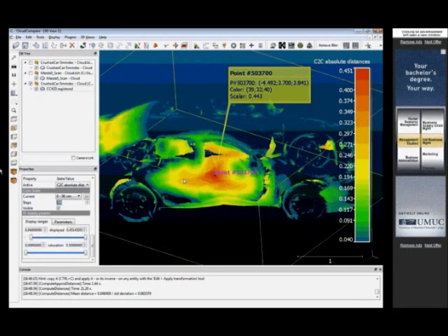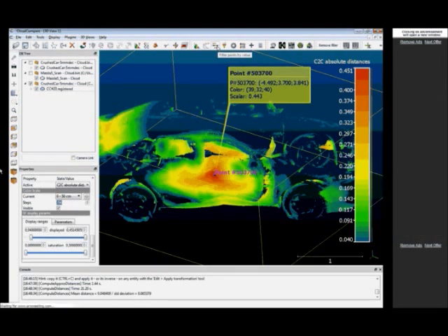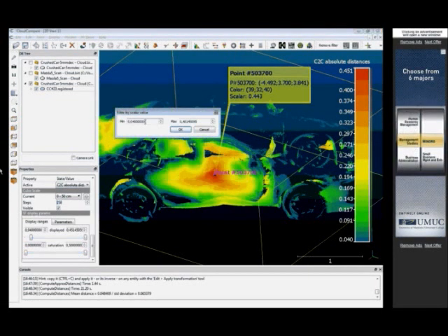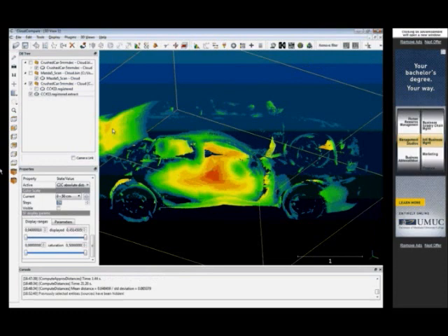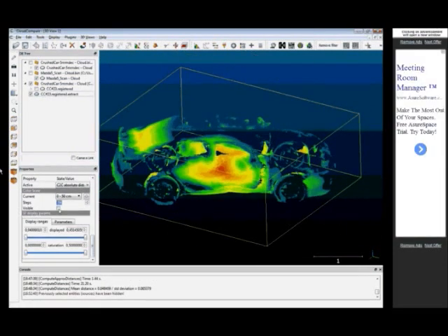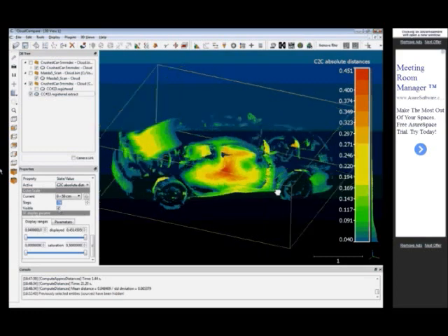There's a method named filter points by value. You can enter the boundaries, any boundaries you want, but by default it will take the display boundaries. So this is exactly what we want. So CloudCompare has created a new cloud. For this new cloud, we must display again its color scale, as it's not the same cloud. And here we are.